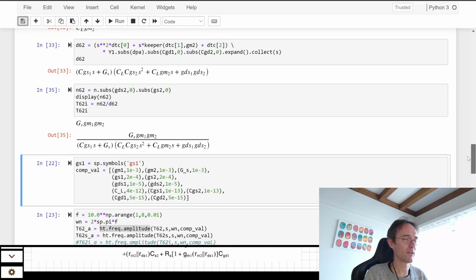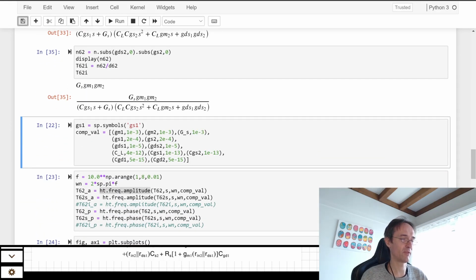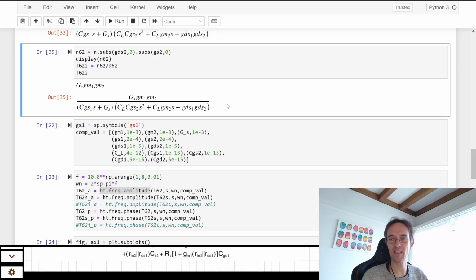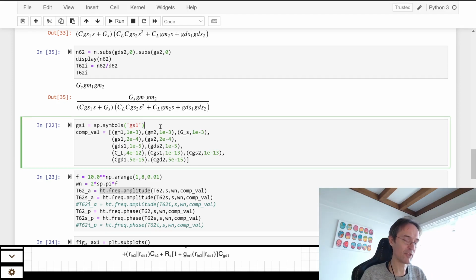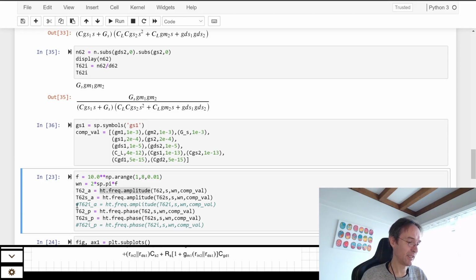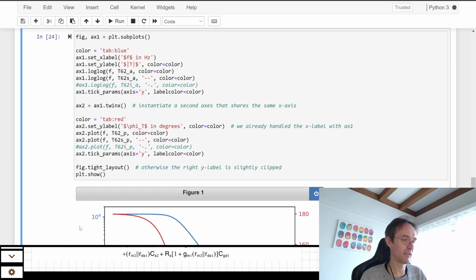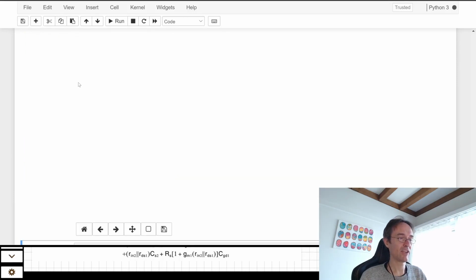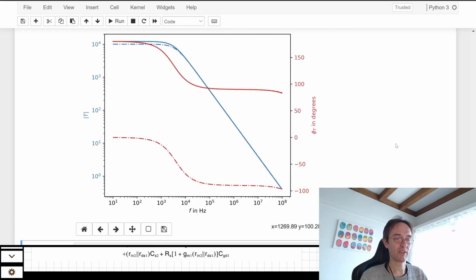But what we have now, those of you who still remember everything you had from system theory or signal processing lectures, you already see that this is a low-pass filter function with one real pole and one complex pole, and you even could now guess the pole quality factor of that complex pole. And to make sure that what we did is okay, I can now simply also draw the signal flow graph of that, signal flow graph as before, and then I can check whether with those values here what I did was okay.